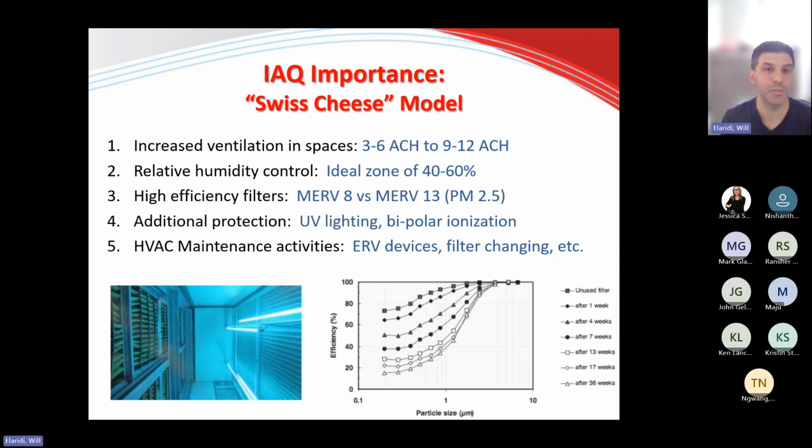By that point, it defeats the purpose of putting fresh air into the building because it's carrying those pollutants along with it, and the filters get warped because the amount of air pressure is sucking in those filters. So that's just an example. Proper maintenance of this mechanical equipment, the ventilation air handling units or ERVs, is very critical.